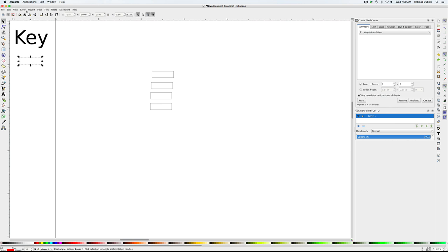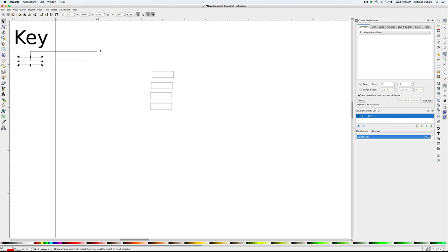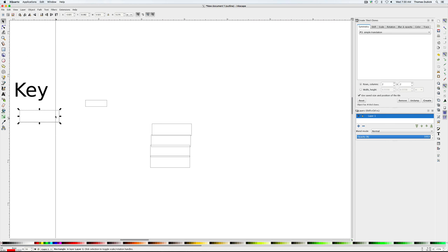Whereas if I took this object and I do edit duplicate, it's going to make it right on top of it, just like the other one did. All right, now watch when I make this one bigger. I'm going to hit the control key and hit this green handle, and it'll do it to scale. It's important you keep it to scale when you do this. See how these changed. These were clones. This was a duplicate. A duplicate doesn't change. All right. Undo scale, undo move, undo duplicate, because I really don't want to duplicate these.